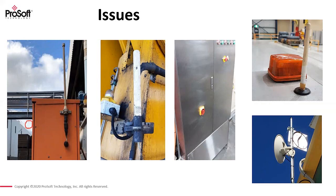This is a standard Omni antenna. It'd be much better to use MIMO and to actually move the antenna away, maybe half a meter or a meter, from that yellow structure.